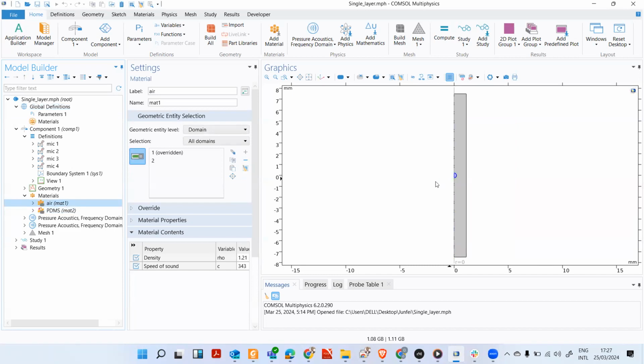So you can imagine I have a small bubble. As long as I excite the bubble at the right frequency, the bubble can resonate. In this case, the bubble's compressibility acts as the spring, and the radiation impedance acts as the mass. So there's a spring-mass system, a single degree of freedom oscillator. When it's resonating, it interacts with the incoming sound so violently that it can do a lot of things with sound, mostly block the sound at that particular frequency.